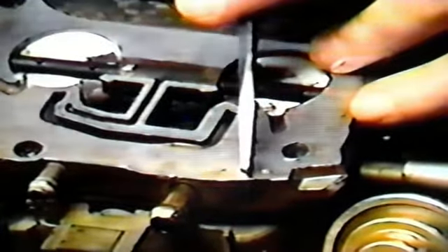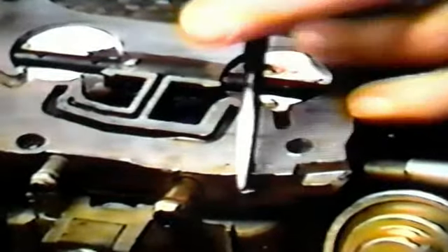Next, take a sharp cold chisel and set one corner into the hole. A sharp blow at this angle will cut a small, clean notch in the carb and pop out the plug all at the same time. This quick, simple procedure helps you avoid the possibility of doing serious damage to the carburetor. As you cut the notch, you may find that a portion of the plug stays in the holes, but don't worry about trying to dig them all out. You'll usually find that the adjusting tools will fit anyway.